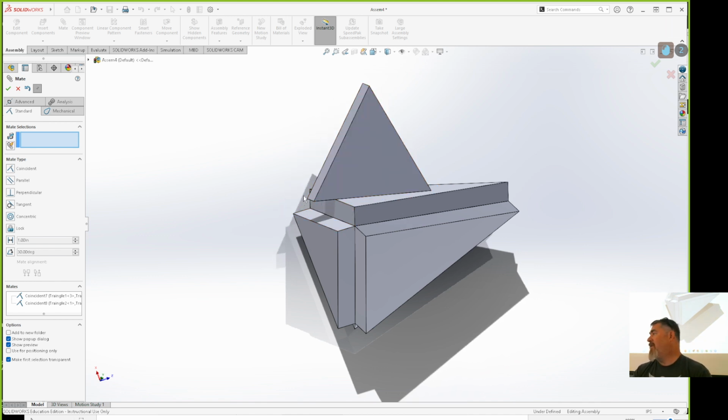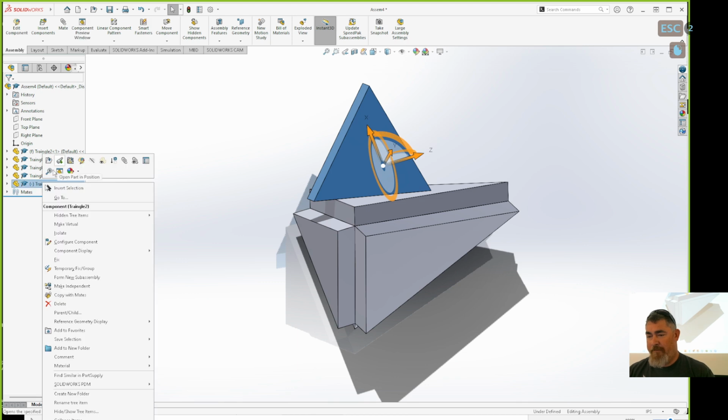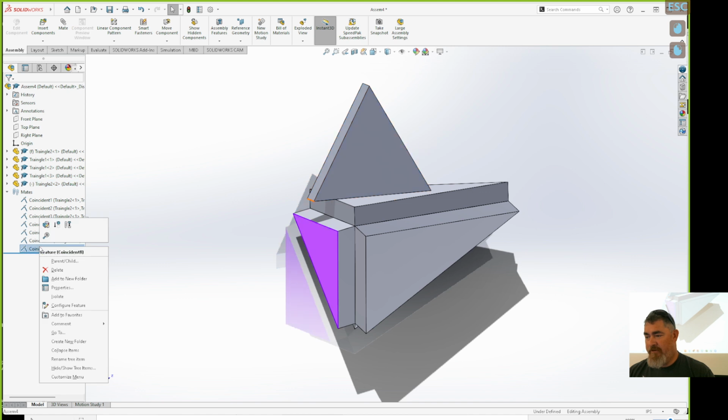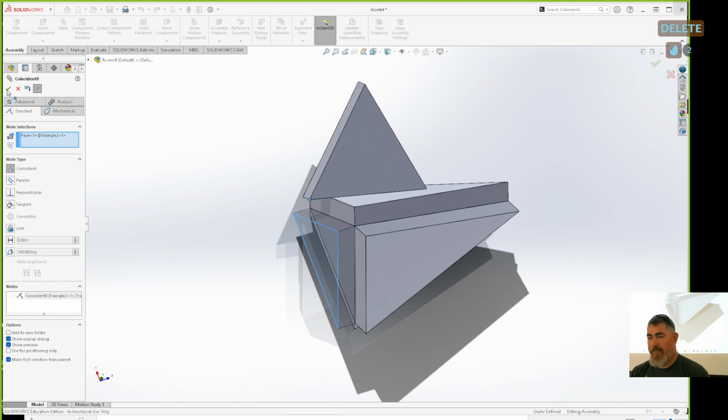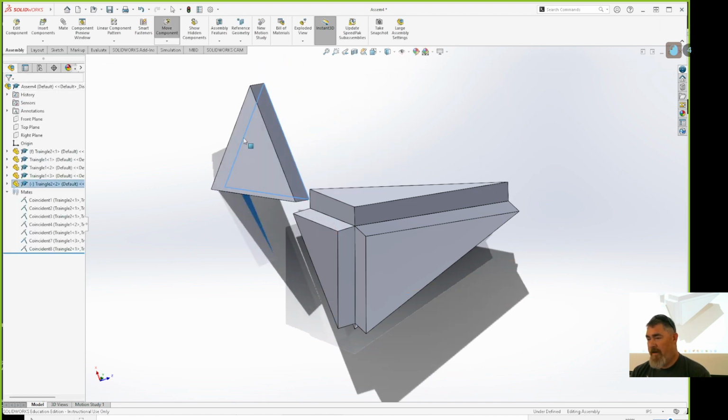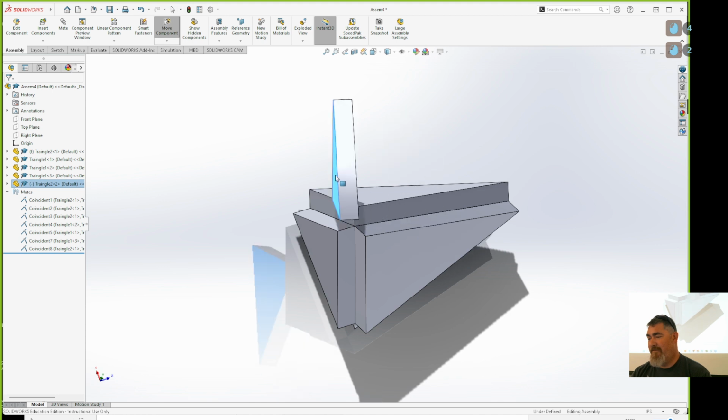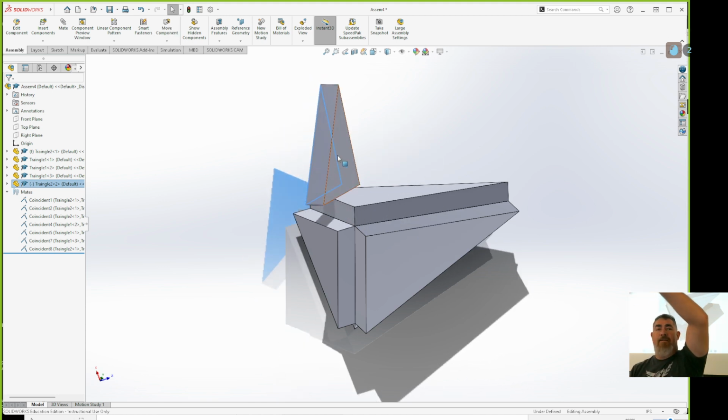So if I don't have an edge there because I can't do faces because I don't have another face to line it up with, I can just pick that edge. Or I could have picked, see what happens if I pick the corner instead. So instead of doing the edge, if I edit that, I pick the corner. Now it can rotate and spin around that. So it's just making that corner stay on it, not the edge. The edge is making two points stay on that face, so it locks rotation. But if I only have one point now, it can still spin around that thing.